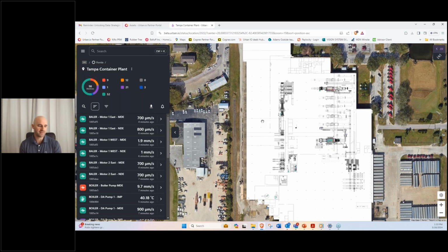But if we have just slabs of cement, walls like that separating rooms, that's not as big of a hindrance as metal. So it reduces our range. Basically, if you put the gateway in a metal box, that's going to cut the sensing range in half. But if you have some metal structures in a facility, the network tries to work around that, but it is eventually limiting us a little bit. But every 30 sensors justifies a new gateway. So if you have 100 sensors on site, some facilities might need 3 gateways, some might need 1.